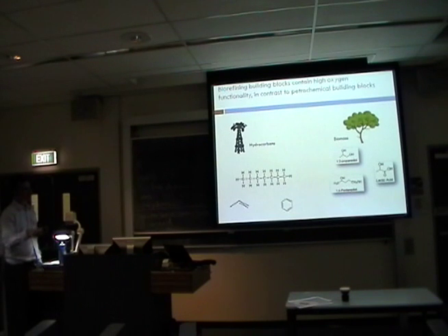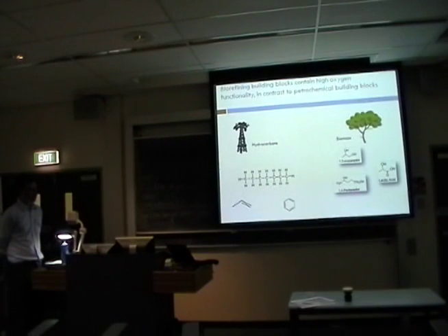All right, with biomass, when you start breaking it down, you tend to get compounds that have quite a bit of oxygen functionality. And what I show here is mostly relatively mild oxygen functionality, actually. You've already removed some of it. The important thing to bear in mind about the oxygenate functionality is that anytime you have a functional group, there's going to be a pretty good tendency for it to want to bind to the types of catalysts that are used in refineries. So it's called a functional group for a reason. It's a handle on which you can do chemistry. And so selectivity is a huge issue in biomass refining, because you have so many points at which you can do chemistry and points at which you can attach too strongly to a catalyst and deactivate it, on these kinds of molecules that are highly oxygenated compared to these kinds of molecules. They tend to be more homogeneous in their atomic composition.